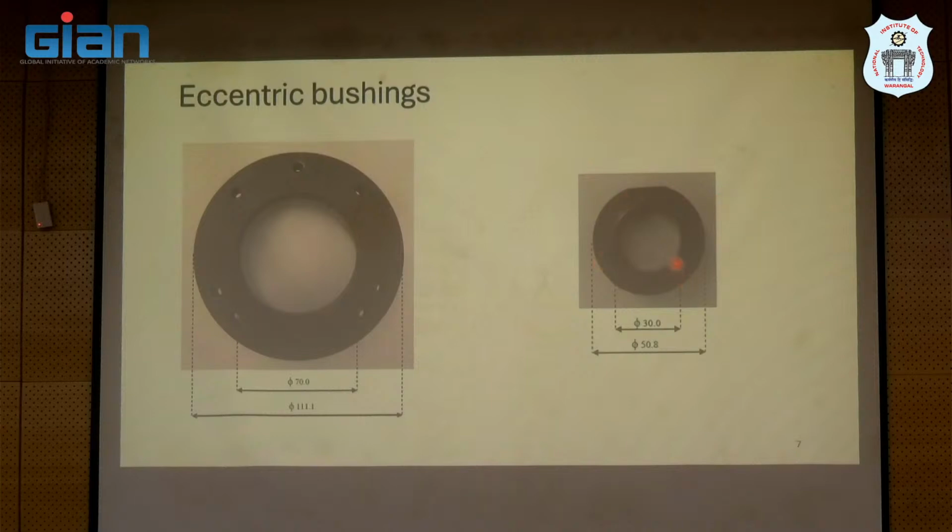The bushing on the right side is a bushing that will help us achieve a wobbling motion of the shaft. When we put the shaft through this hole, it is not circular, it's elliptically cut. So you will see that the motion will be wobbling. So you will get dynamic eccentricity. And the margin, or the way it's eccentrically cut, will determine the dynamic eccentricity severity. Okay? So what you will do is take the original motor, replace this enclosure, and change the end bells.